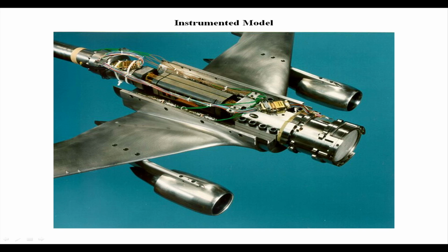So while you fabricate this wing or say this engine, if you are interested to find out how the pressure looks on different regions, then you have to plan those components in such a manner that they can be split apart. Tubes could be inserted, again they can be put together, and then those tubes should be running through those surfaces, that means inside, and then finally finding their place through the fuselage portion and out of the support system, so that you can take it to the relevant device and make the measurement.